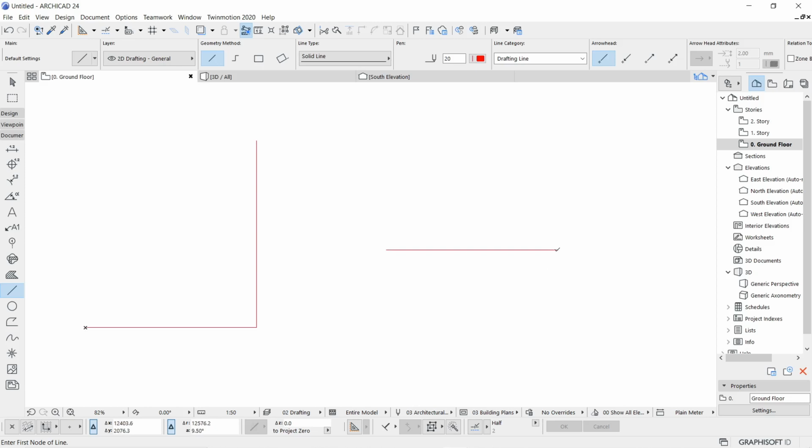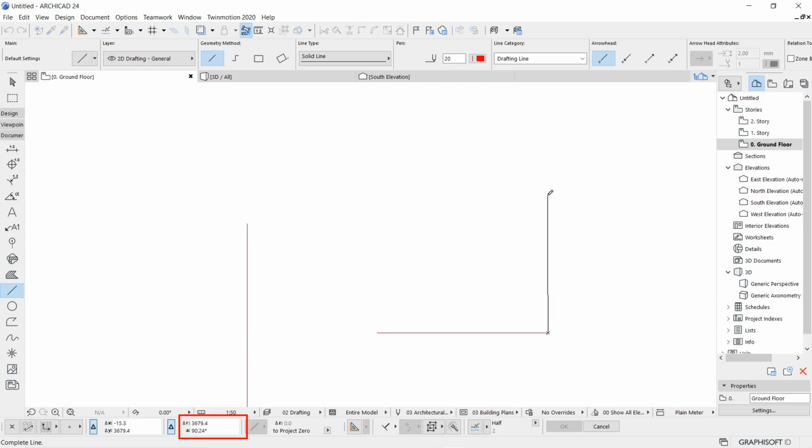And now I'm going to click one more point, that is the end point of this segment, with the check mark. And this time I'm going to travel upward. You can see the A at the bottom shows nearer to 90 degree. That means a vertical line. So you can use this pan tool, that is, hold the mouse middle button and drag your screen down. These are zooming techniques you have to follow, which are very common in any CAD software, like the wheel button to zoom in and out, or press the wheel button to pan. So very much a standardized thing.